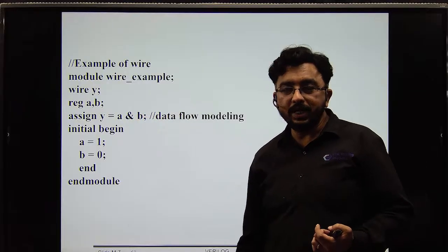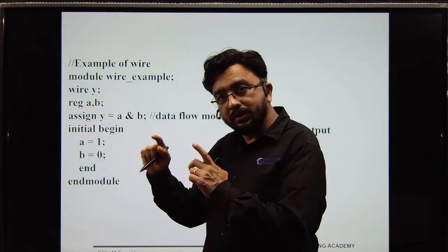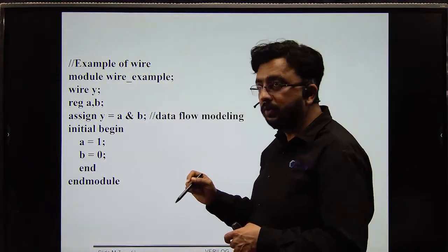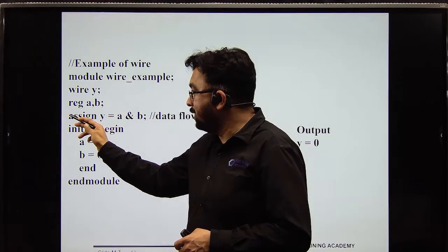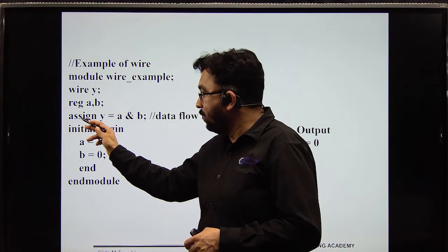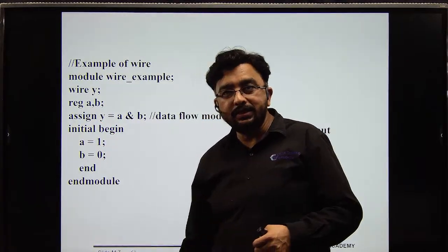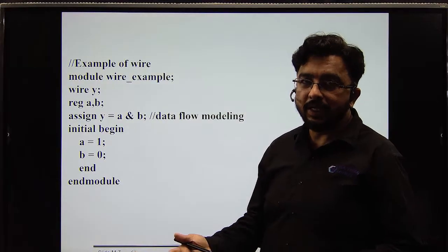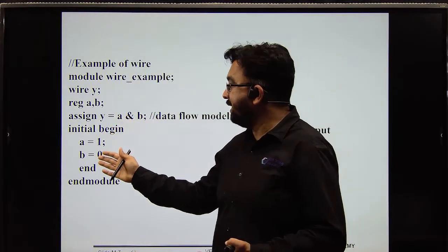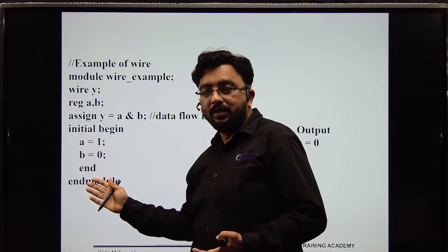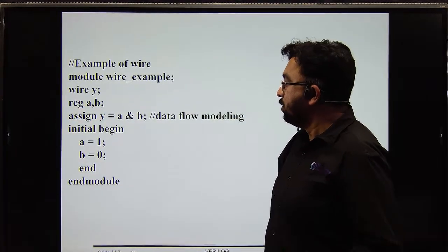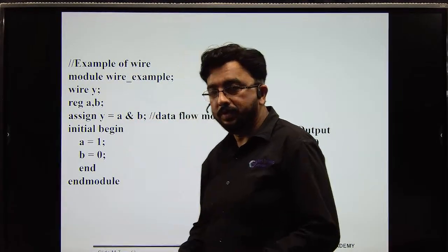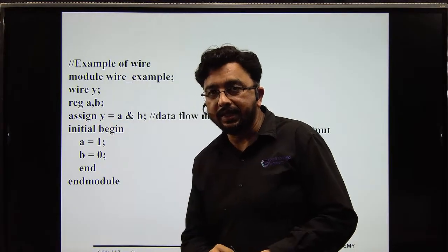Okay, so in upcoming classes you will come to know that you are not going to use the keyword assign inside the initial and always blocks, because there is a particular purpose for that. We will discuss it later on. Okay, so this is a simple example of wire with the help of the keyword assign.